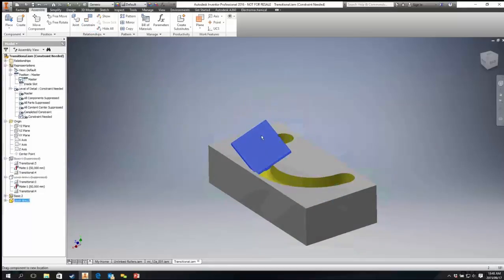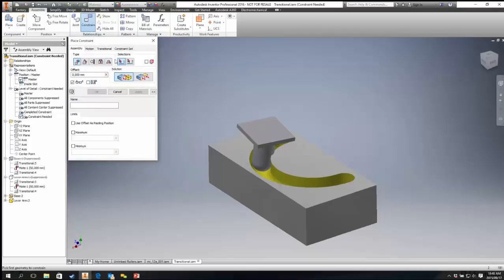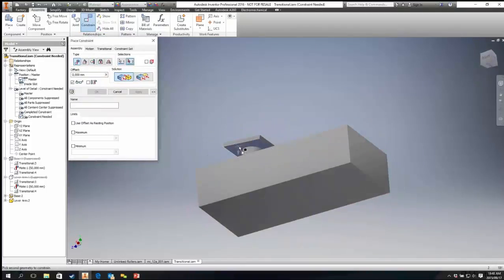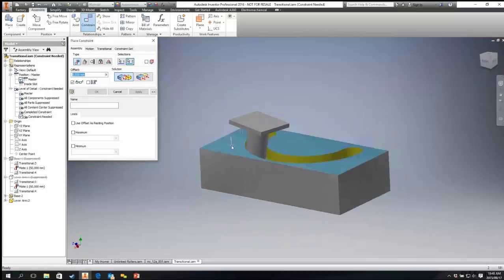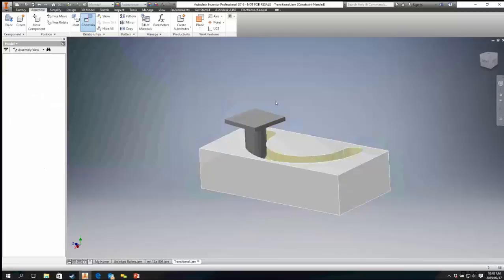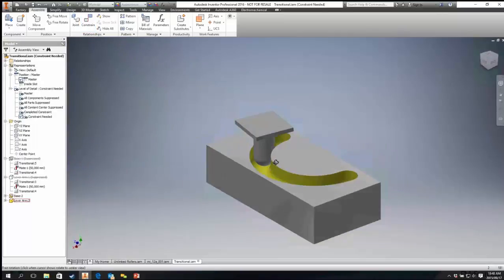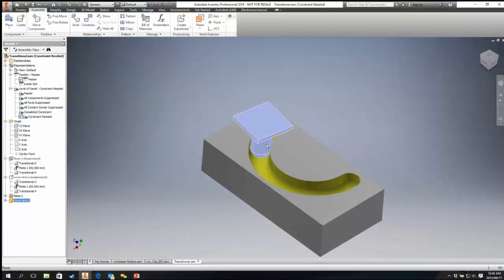And you see that it's sliding and rotating and then all of a sudden jumping on the outside of the object. It'd be terrible to try and work with something like this, which is why before I insert that constraint, I'll already set up some boundaries. I'll say that I want an offset between this face with the mate constraint to this one at, say, 50 mils. When I do that, it's already linear, so it's aligned, and I can now position it briefly, roughly where I want it within this pocket, okay?